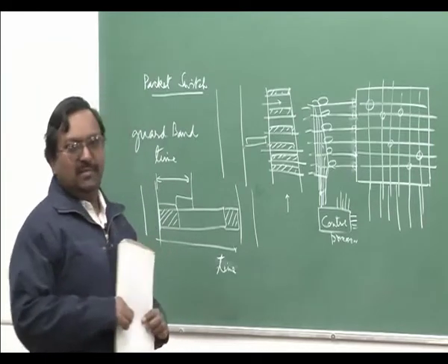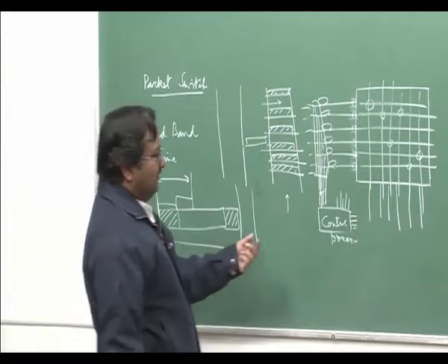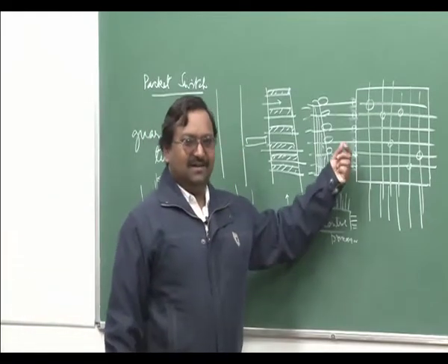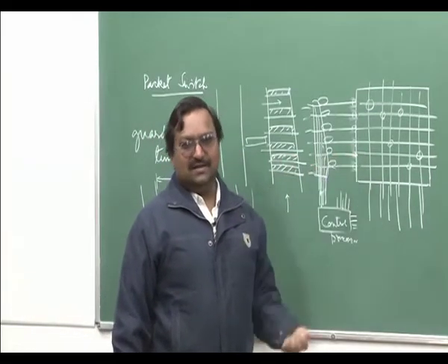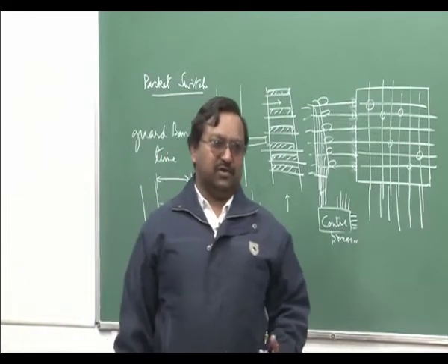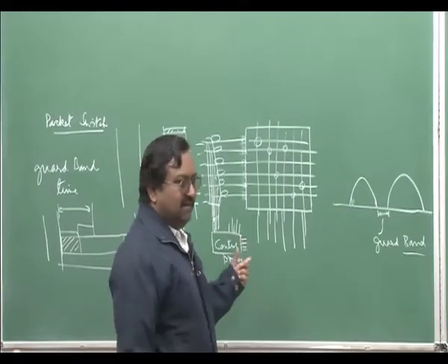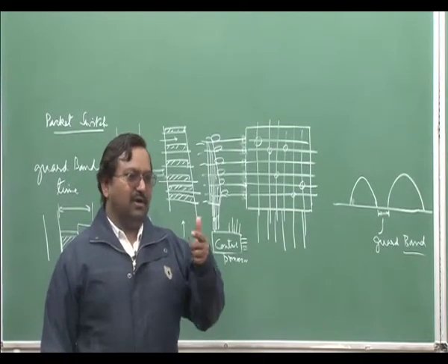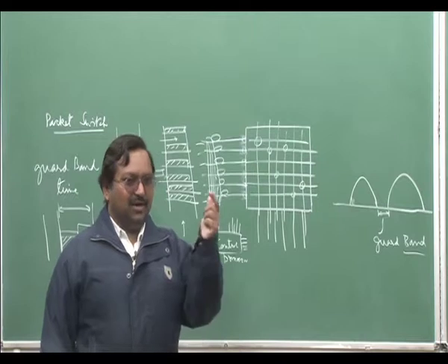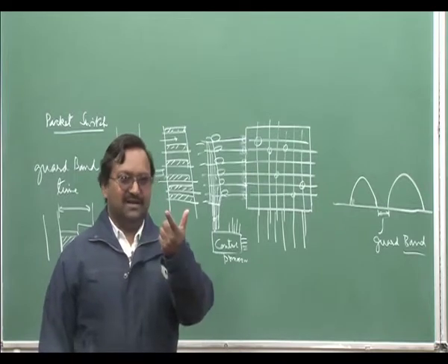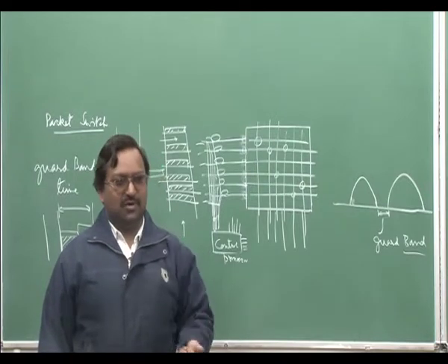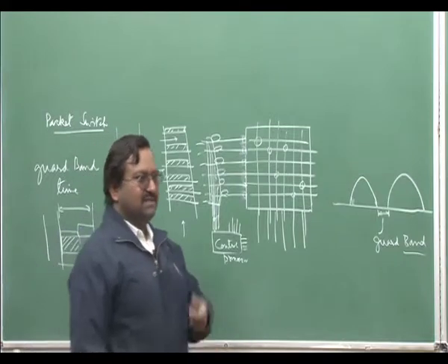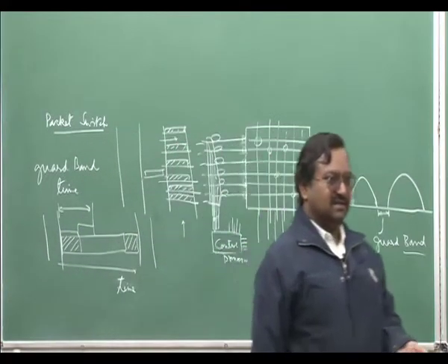That will depend on all your circuitry, the time which is required here, what the tolerances are in activating and deactivating the cross points. Because remember, activation also means you have to first of all do the row and then column, and the row has to go down and column has to be kept up for one slot period when the cross point is active, and then the column has to go down. So, these just take time, they cannot happen instantaneously.